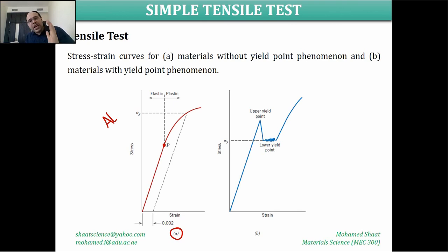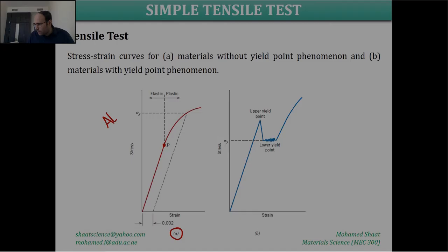Beyond this straight line, a curve will start to form in the relation between the force and the elongation, or the stress and the strain. And here we have a smooth transition, as I mentioned, from the elastic to the plastic behavior of the material. So the question is, where is the yield point, or where is the yield region that distinguishes the elastic from the plastic? Definitely, once the material finishes its proportional or linear relation, to the left of this point will be counted as elastic behavior of the material. Beyond that point, this will be counted as plastic deformation of the material.